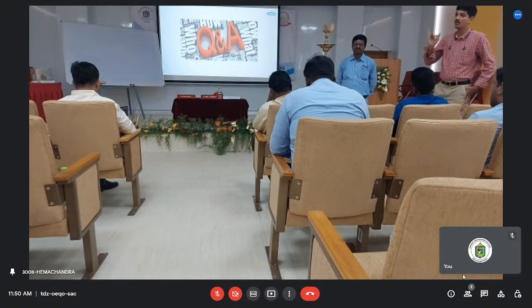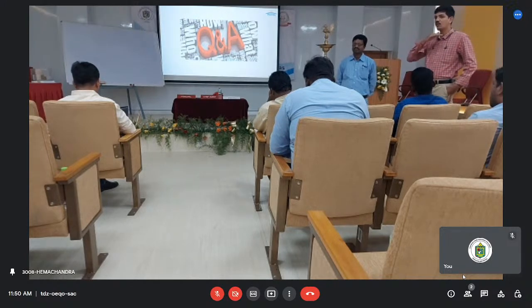Dry film thickness, even if you check, we have to take it on average. But basically what we tell is, because our floors are not leveled, either it is terrace or internal bathroom, it is not leveled. A lot of slight undulations will be there. So if you calculate consumption, it will be good.